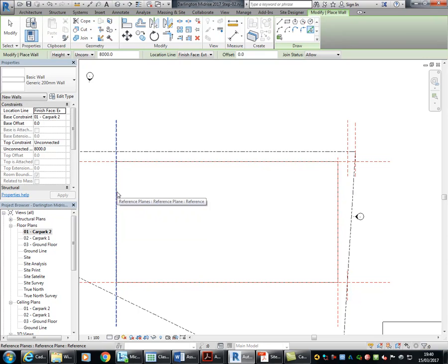Yeah, that's right, it should let me do that, but the reason it's not working is because my building pad's below the view. So my building pad's down below the level I'm working on, so it won't let me pick it. Normally it would though, that's the trick I wanted to show you. But let's do a rectangle instead.